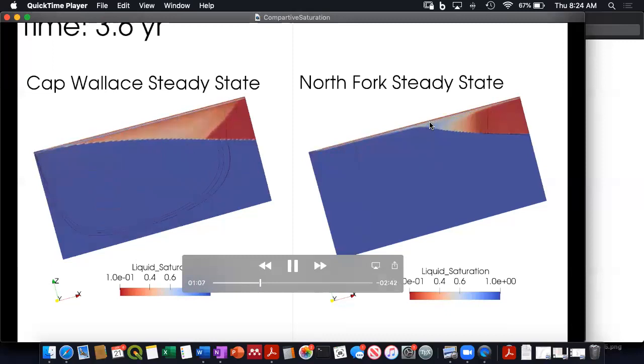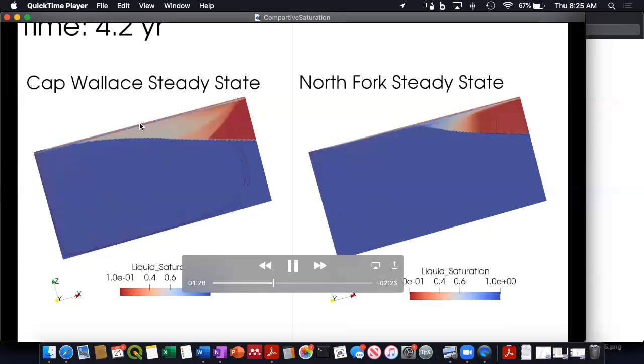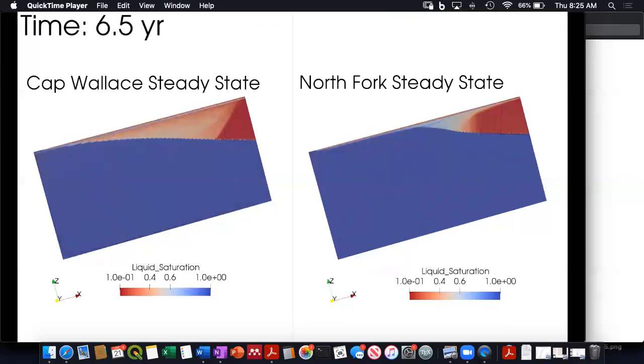It's a little more, the configuration changes depending upon the contrast. So this is just to give you guys some sort of conceptual idea of what the water movement looks like in a hill slope. It's saturating up in the soil, all right, and it saturates quite a ways up the hill slope. And then some of that moves down into the bedrock, becomes recharge, and recharges this groundwater system. Now, during the summer, you'll see the soil dry way up, all right? So the soil dries up and the groundwater table configuration basically stays pretty much the same. You see a little bulge during the spring and that drains down a little bit, but the groundwater stays very stable. And this is 10 years of spring snowmelt and then summer precip and dryness.